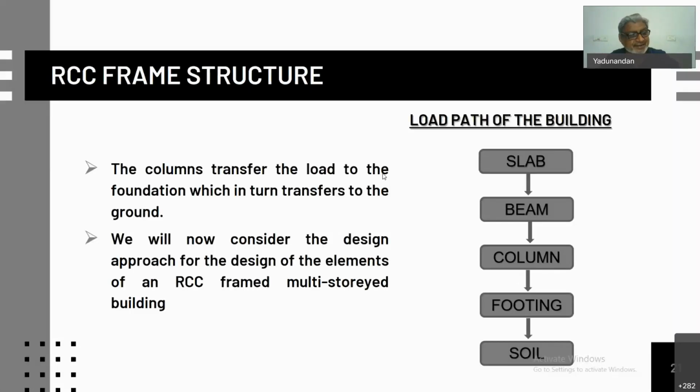So generally, the load path of the loads in the building is from slab to beam, beam to column, column to footing, and footing to the soil. The column transfers the load to the foundation, which in turn transfers it to the ground.